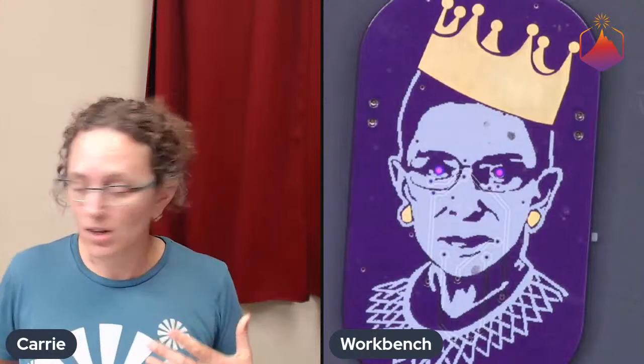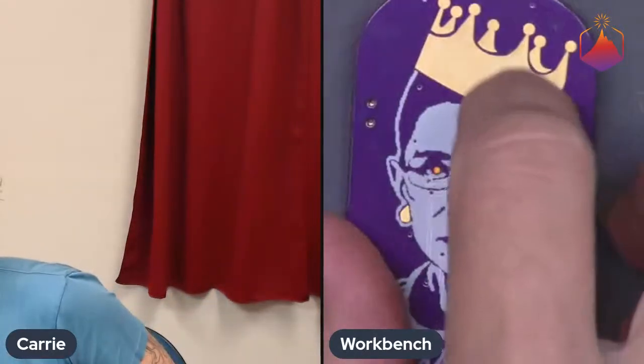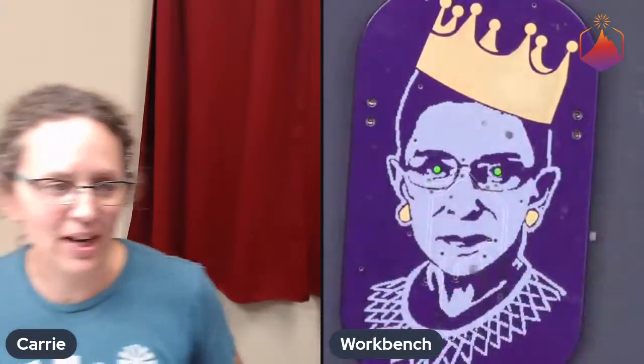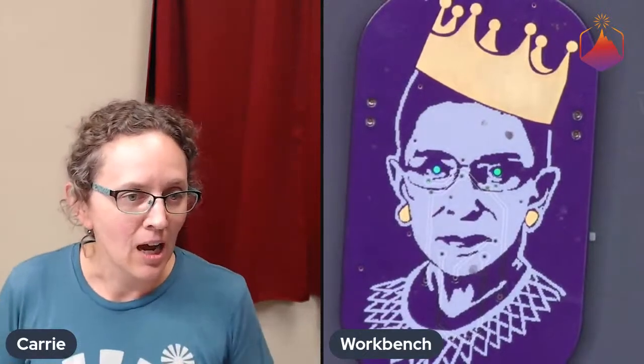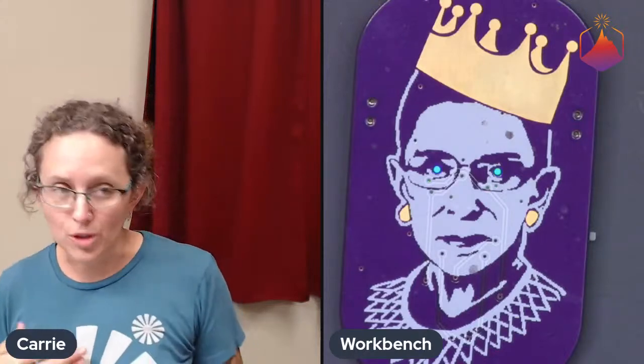So, yeah. Anyway, basically what she's made up of, and we have some blemishes from manufacturing and stuff. Basically what you're looking at is purple solder mask, which is over most of the copper on the board to protect it and to keep anything from shorting out. You're seeing white silkscreen, which is usually used for component markings, that makes up her face in the main part of the graphics. And then the gold is exposed copper that's been gold plated over.